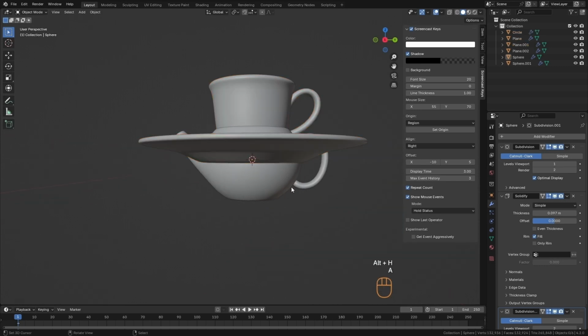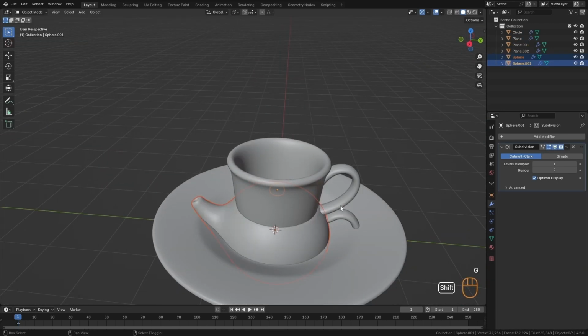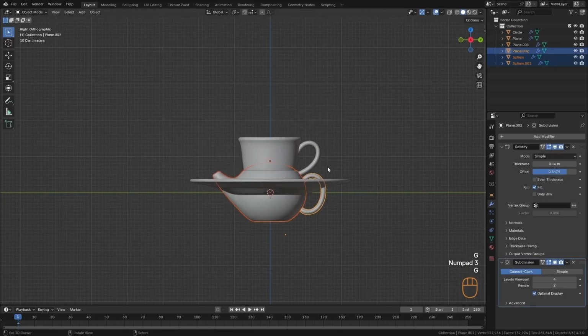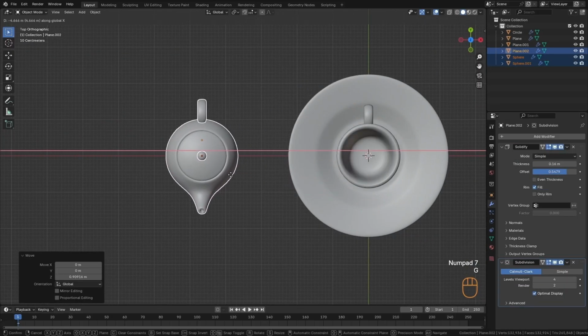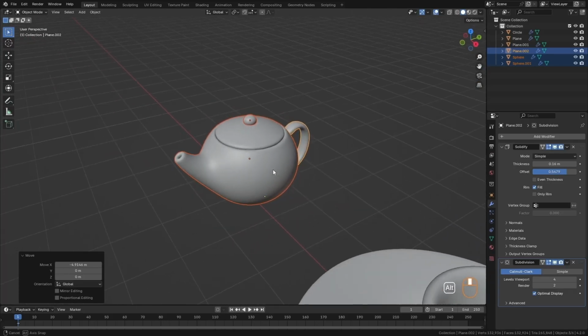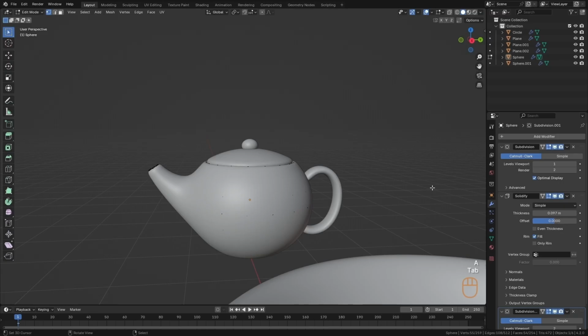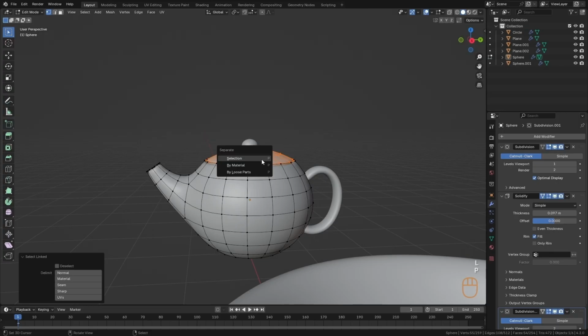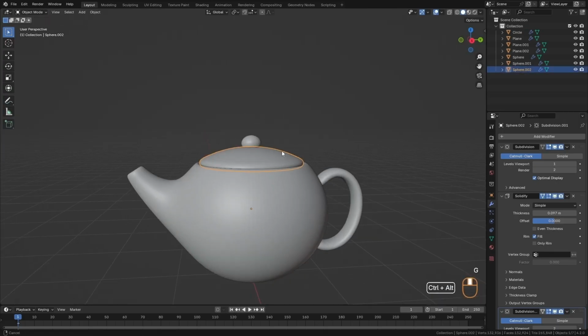I'm going to unhide everything else with Alt-H, and then all that remains is to adjust the scale of my objects. I'm going to select all the objects of the teapot, move it upwards. I'll move it over here. And something we can do to better manipulate objects is to parent them. For instance, I'll separate this lid from the model. So I'll activate the display here. I press L, and then I press P. I'll separate the selection, and it will remain separated.